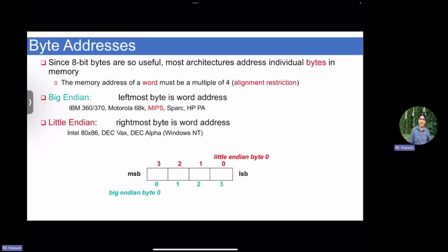That like there are some cores that are very well known to be RISC-V used, and there was a bug that took 3 months to discover, and at the end of the day, we discovered the core is little endian, but the actual memory is assuming big endian, and there is a mess somewhere in between that they forgot to translate, right? So it's a bug related exactly to the slide, and it takes a lot of time to figure out because you will not.